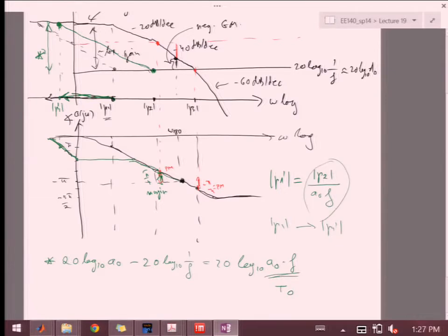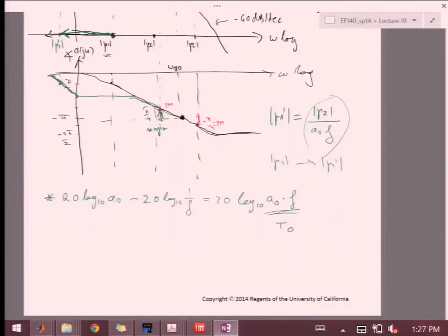What ends up being the case is the C's that you add are on the order of 1,000 picofarads, which are some pretty large values to be adding to integrated circuits, in terms of capacitance.